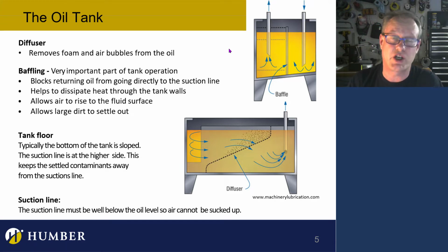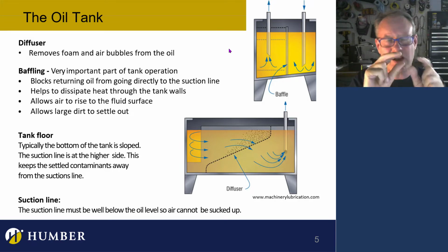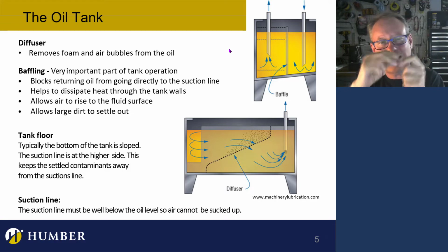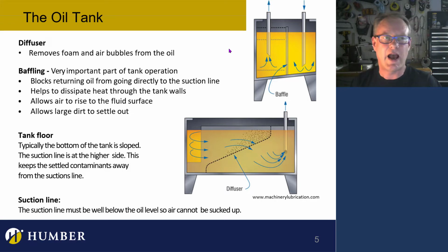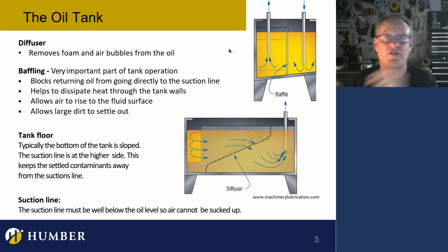Now this picture doesn't show a drain line, but I think you know what a drain is. The drain is another line that comes out of some components and carries just a few trickles, a tiny bit of liquid. Like in spools that move back and forth, liquid gets stuck around either side of the spool, and sometimes it has to vent out of the system or out of the valve itself.